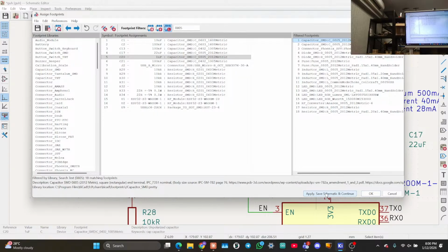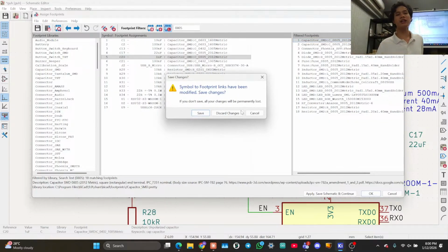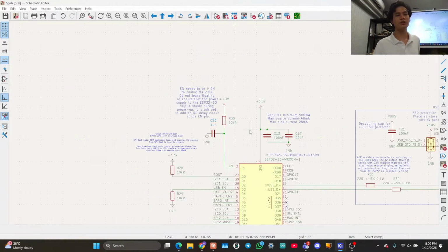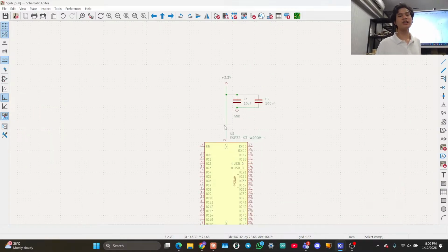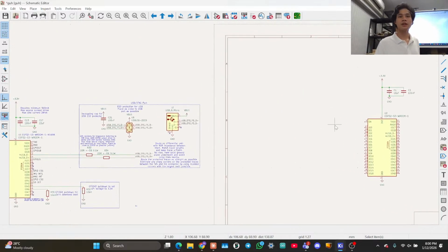Okay, so whenever you have anything which is going to draw power at random, irregular times, it's usually a good idea to put a decoupling capacitor. It doesn't really cost anything. It costs a little bit of board space, but I don't know how many of you are making super tiny PCBs, so it's probably fine. So just add a decoupling capacitor if you're not sure. Alright? Check the datasheet also. Sometimes it makes things worse. But rarely.